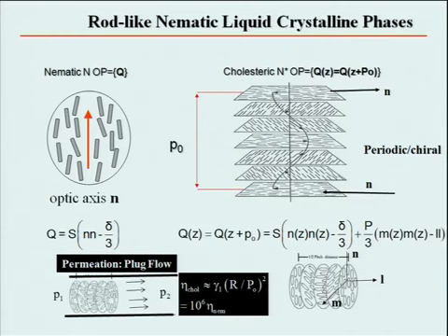So the viscosity will decay to the normal nematic values. But at low deformation rates, the viscosity is 1,000,000 times bigger, and therefore it is a useful property for viscosity modification without adding any other components.